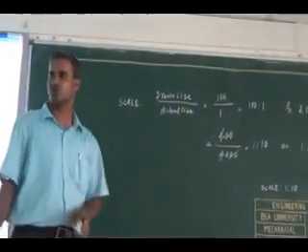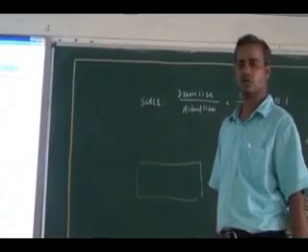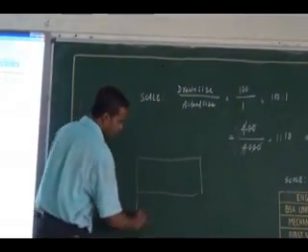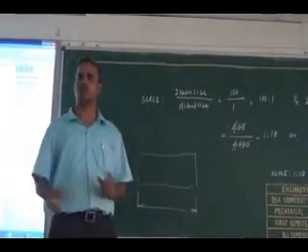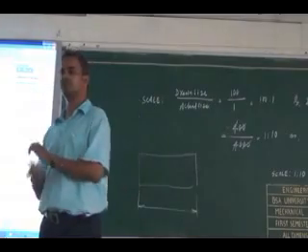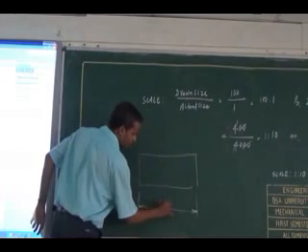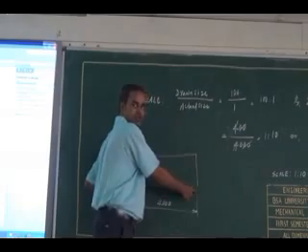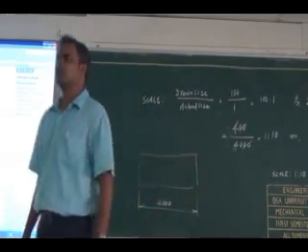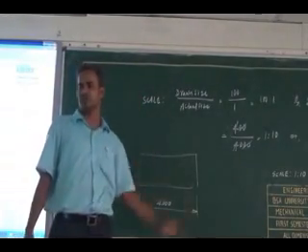One thing you should remember: whatever drawing you are drawing, say this is one view of the machine, the dimension you show in the drawing should contain the actual length of the component. If it is 4,000, I have to mention the dimension as 4,000 mm, even though the length I measured to draw it is only 400 mm. Is it clear? This is about the scale of engineering drawing.